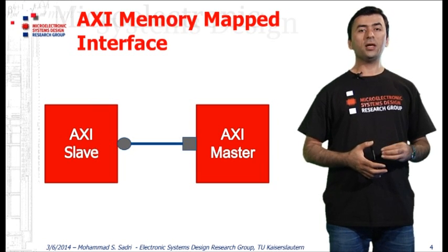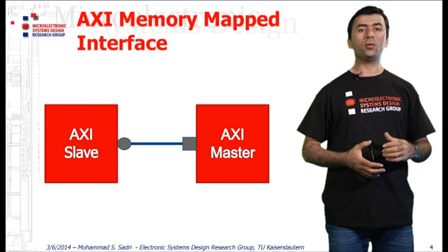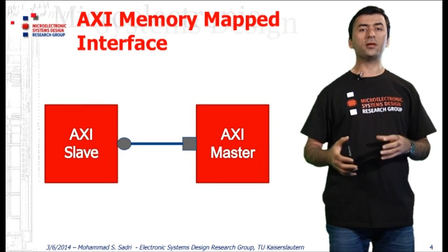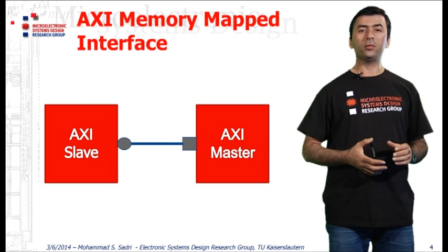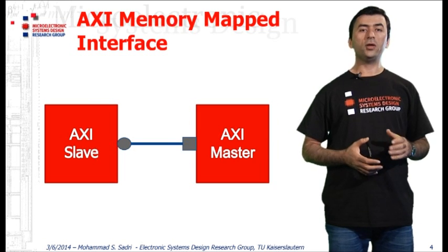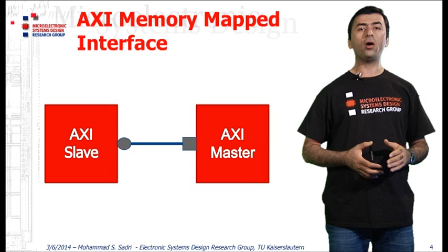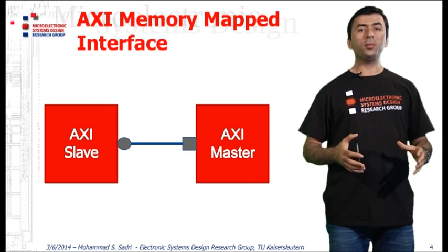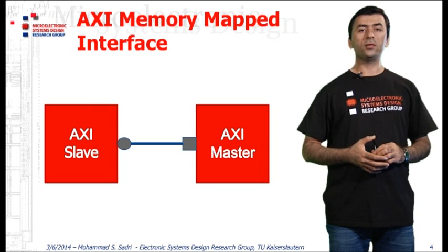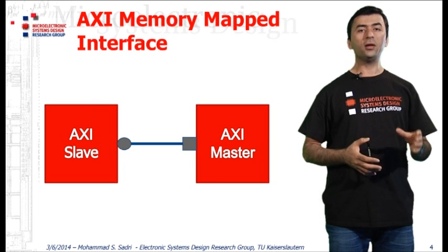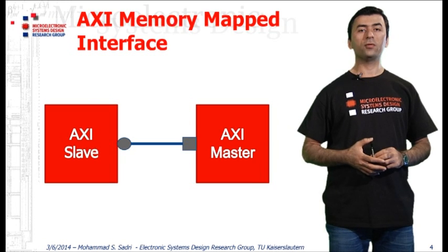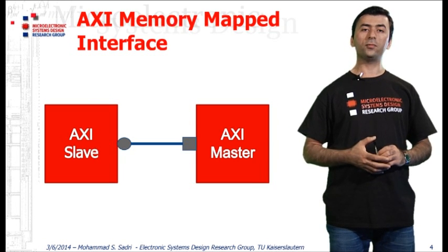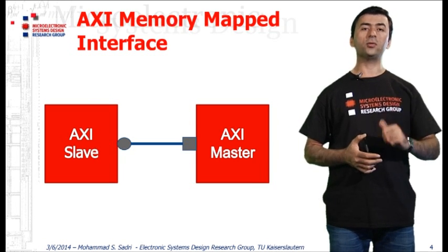Towards this, we need a kind of a standard based on which all of these IP blocks can talk to each other. So every IP block cannot introduce its own way of talking to the outside world. All of the IP blocks that everybody designs should obey one specific set of rules for receiving data from outside world and transferring data to the outside world.